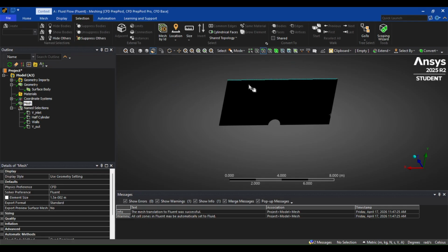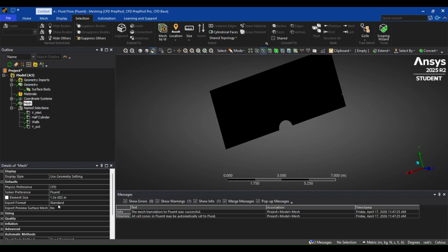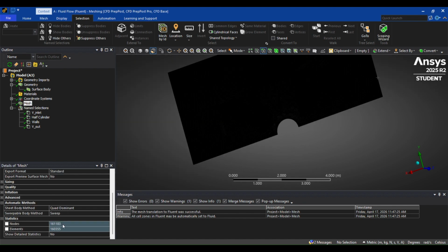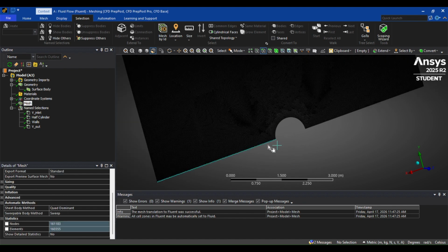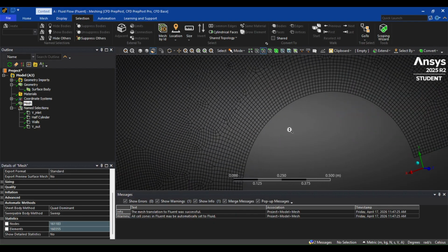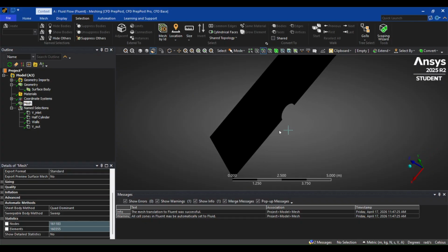So basically all I really did was I came into the mesh settings and played around with the element size until I got to 1.5e-2 meters. What this gave me is 320,000 total elements, which is under our limit as a trial student, and it looks to be fairly precise, so I'm going with this.